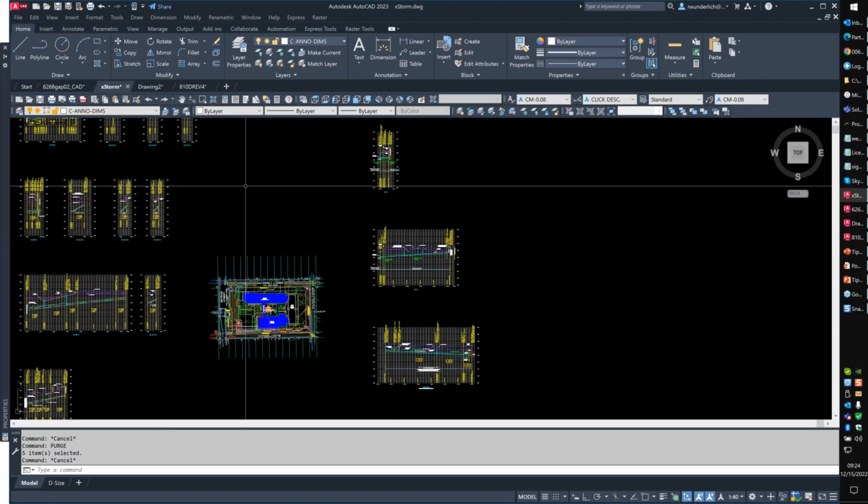Will they be purged if they are on layer 0? Yes. Anything in here, but there are 2 layers you can't really ever purge. Layer 0 you can never get rid of, period. I did cover that in a previous webinar in my 2021 series where I talked about what's so special about layer 0. And Lori will have a link where you can go back and see those.